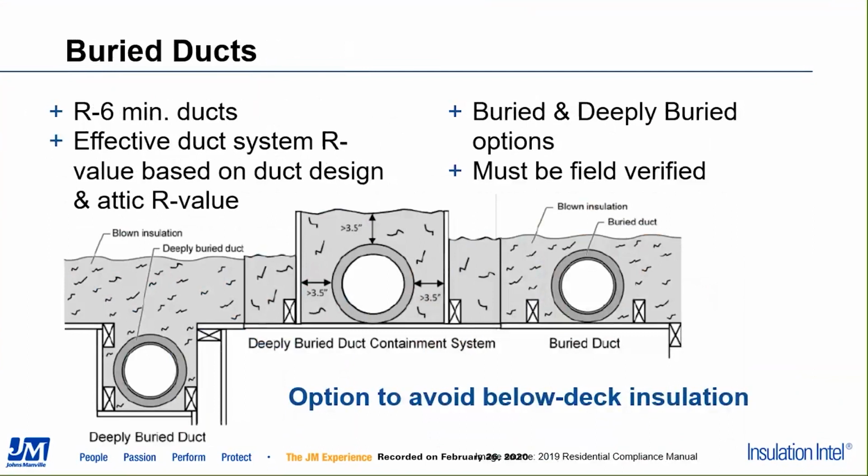Real quickly, related to attics is buried ductwork. The image that we've got on here actually comes from the Title 24 Residential Compliance Manual, and historically, the image on the left is really what needed to be done. What buried ductwork allows you to do is let your ductwork be considered to be in conditioned space, even though it's still technically in the attic.